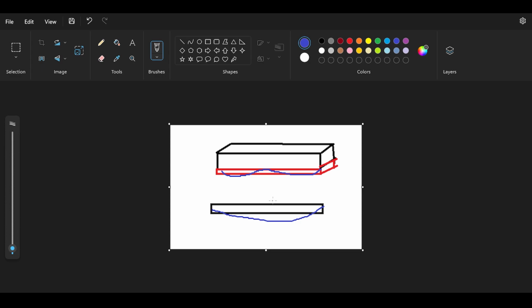Now, what you would do is you would flip the beam. When you install the beam, you would rotate the beam in such a way to have the imperfection going upwards, because an upward imperfection is amazing for you. This is like a pre-stressed camber, meaning that if you apply a force, the deflection is going to be less because the element is cambered upwards. Of course, here, if it's cambered downwards, the deflection will increase. So in steel, it's your decision.